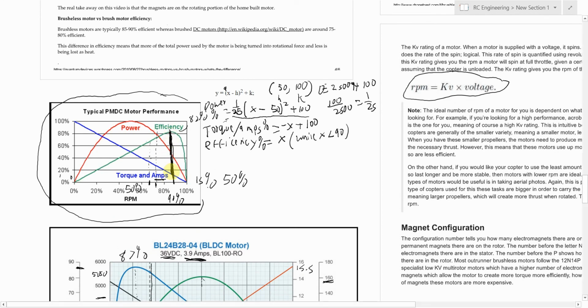So they're running the motor at max efficiency, and then when you do a reduction gearbox, it depends on the tooth count of the difference. For example, let's say the gear on the motor has 5 teeth, and the one on the end gear has 50 teeth. That is 50/5, otherwise known as a 10-to-1 gearing ratio. What that means is your RPM will drop on the output by 10. So since down there it said 40,000 RPM max, you divide that by 10, which means you're only getting 4,000 RPM on the output shaft.